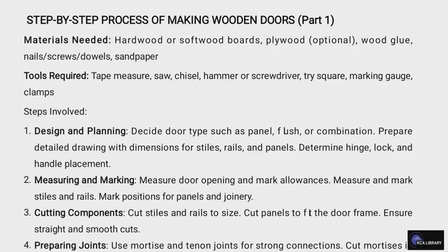The next step is measuring and marking, where you measure the door opening and mark allowances. The next is to cut components. You cut the stiles and the rails to size, and cut the panel to fit the door frame, and ensure that it's a straight and smooth cut.